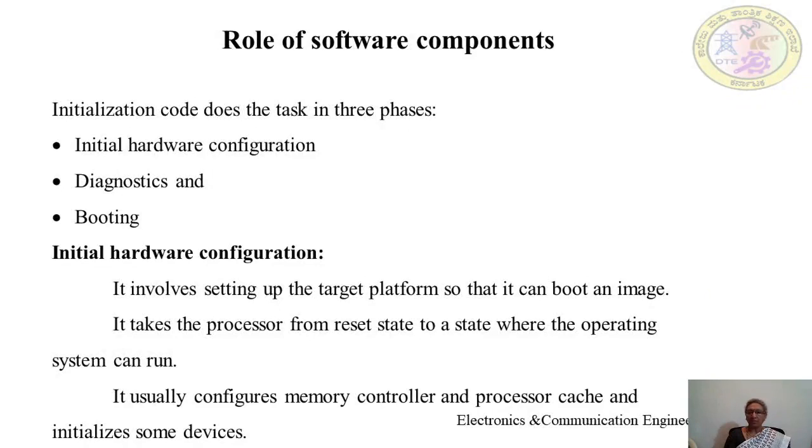Suppose this resides on the RAM, then considerable speed of operation can be achieved. So, systems have a method where initially the operating system runs from the ROM region, and one of the first tasks done by the OS will be to load an image of itself onto the RAM area and transfer the control to that image.